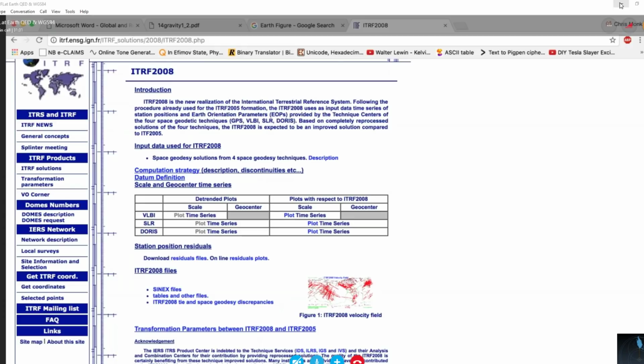So what do you mean? Well, every shot you take, you level your transit, take a straight line of sight to your target, measure the angular distances as far as the distance to the target, as far as the elevations and angles, and calculate it out. And then you just survey it using straight line, Euclidean trigonometry.